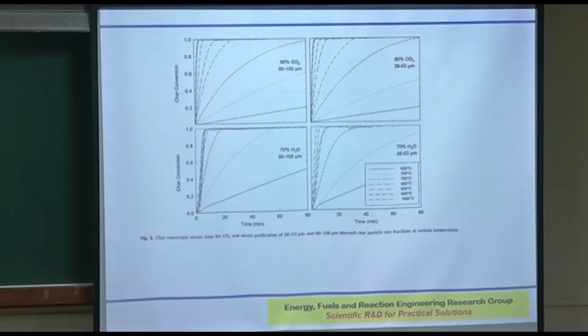Looking at the 6th, 7th from the bottom, between 750 and 800 there is a huge jump. It starts to convert much more quickly. Below that, nothing much is happening, almost the same, slowly. So from 750 onwards it jumps, then at 800 or 850 it becomes even faster, and then at 900 it becomes even faster, and at 1000 degrees it becomes almost instantaneous.